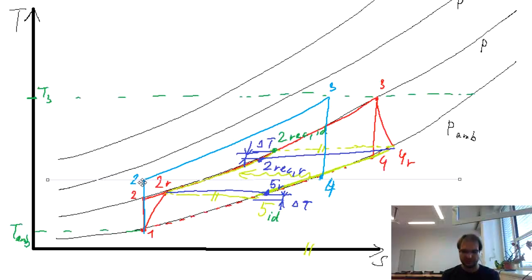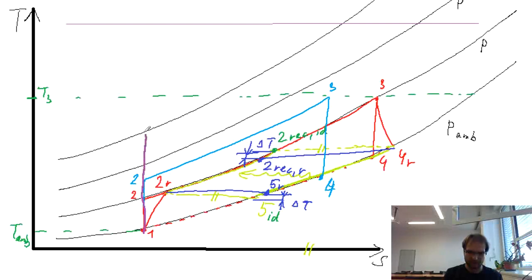And if we increase the pressure beyond this point, if you would have cycle with pressure ratio, let's say this high, there is no space for the recuperation, but in the way that we have the recuperation defined, that the beginning of the recuperation is at the point 4.